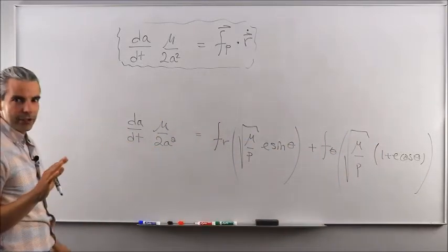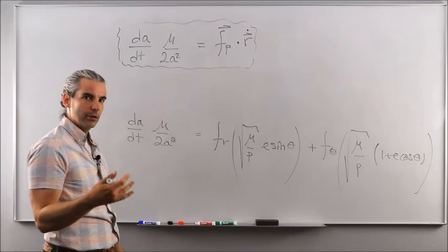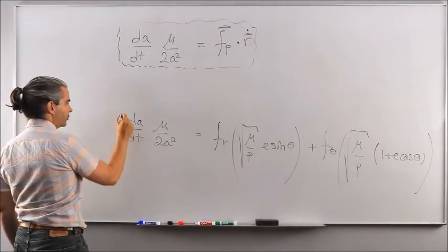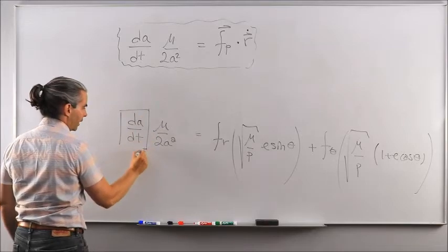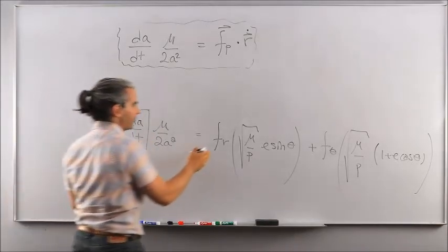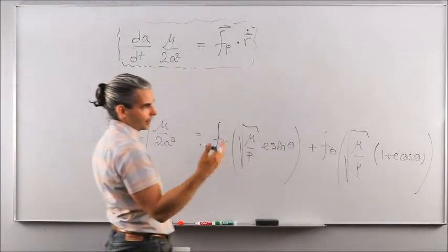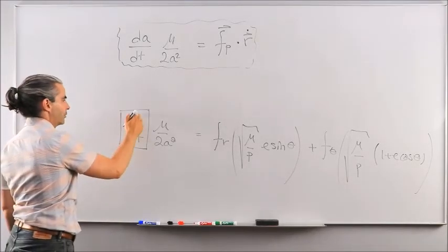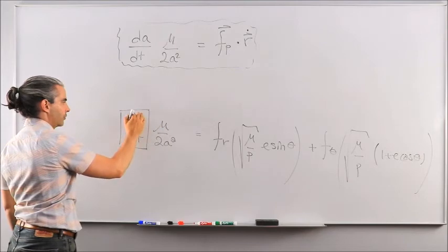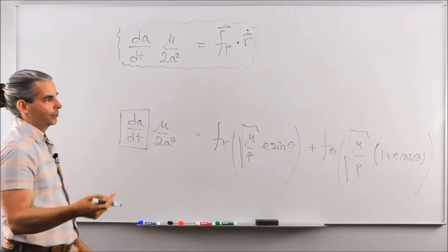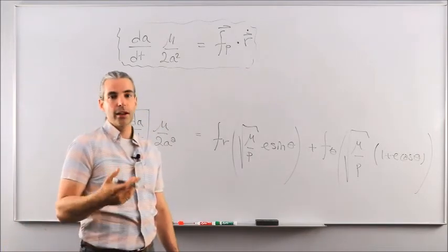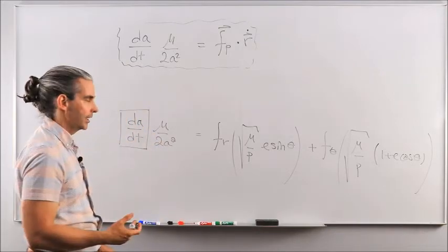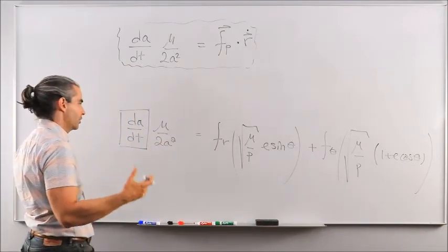Now, our objective here was to derive an analytical expression that would allow us to predict the rate of change in our orbital elements as a function of f_r, f_theta, and f_z. So in other words, finding or solving that expression first for dA/dt, then doing a similar process and ending up with de/dt, and then another process for inclination and so on.